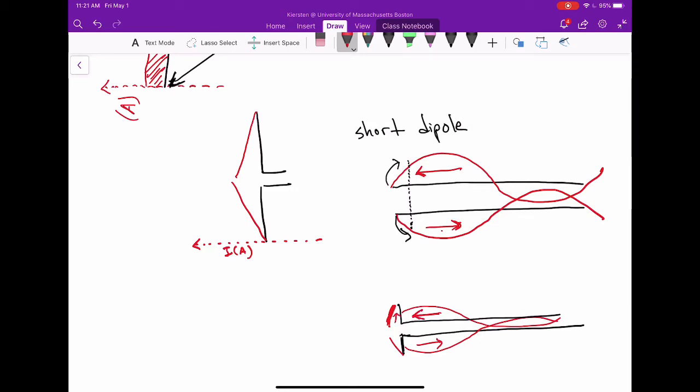And the current on the lower part of the conductor, remember this is the end, it's going to go up also. So they're oppositely directed on the transmission line, but because we fold the top wire up and the bottom wire down, they are co-directed on the body of the antenna, and that's what allows them to radiate.